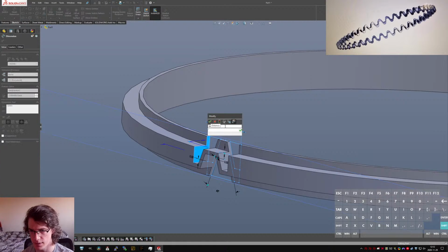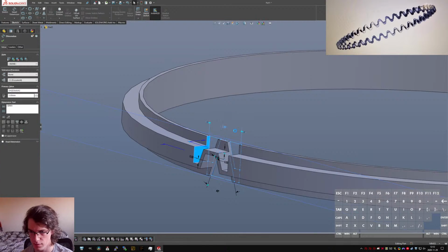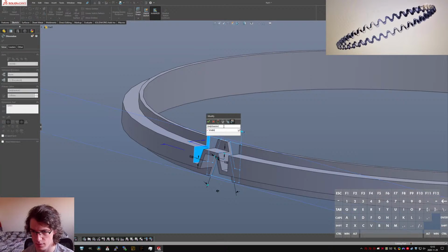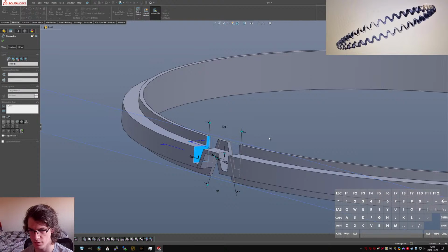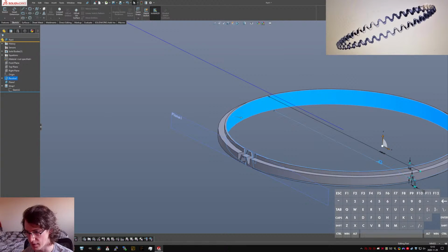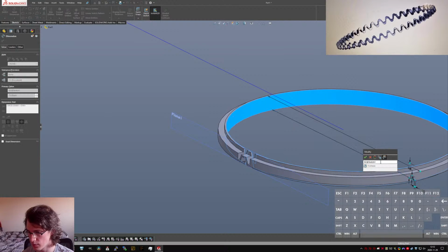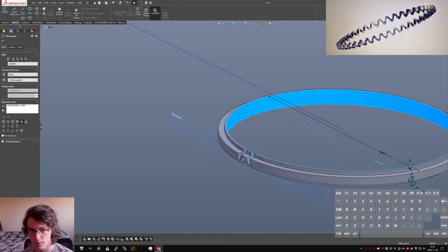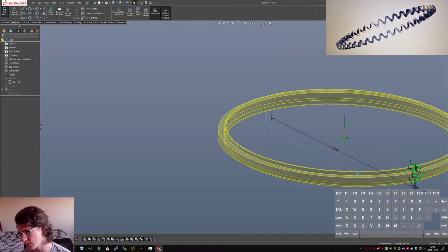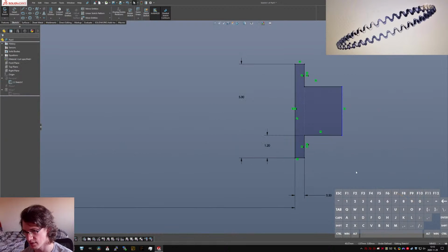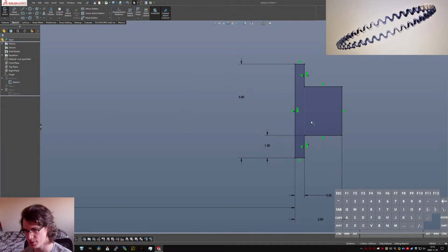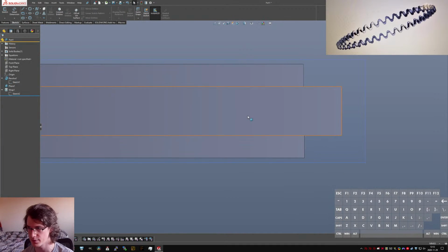No, in here, I could just go width. Whoops. Forgot you need to do equals width. That locks it to the global variable. And then I'm going to come over here and make this equal to ID, which should save me some silliness. I'm also going to be a little more careful, and I'm going to tweak this guy. Instead of having it be a defined OD, I'm going to have it be just some separation, so I can change the OD and it should fix itself pretty nicely.